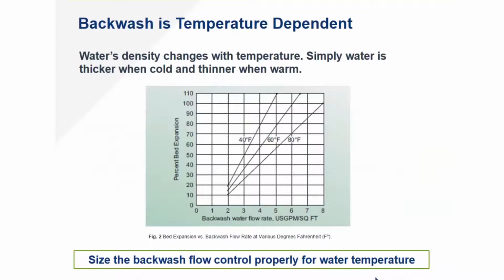So if you're having issues where you're losing resin life or resin capacity, or your activated carbon filters aren't getting clean enough, take a look at your water temperatures. This may be a fundamental issue to your backwash. You may need to adjust the time. I had to do this in my own softener at home, simply because the dirt load changed. My municipality went from doing iron pretreatment to stopping iron pretreatment. So I have a much greater dirt load in my softener than I did before. I had to add a couple minutes to it to get it clean again.